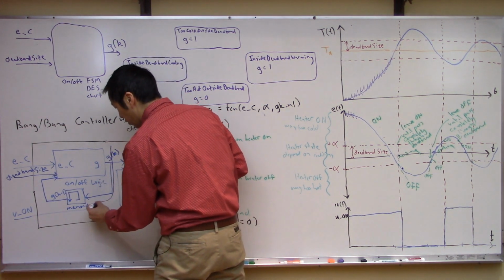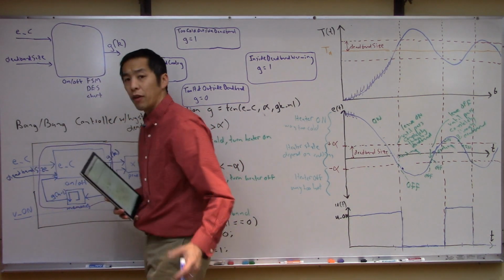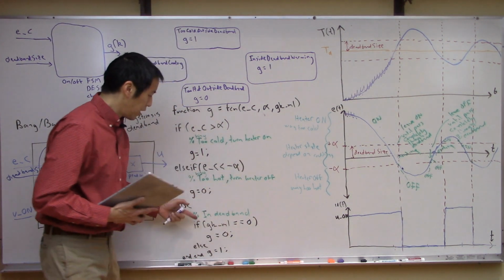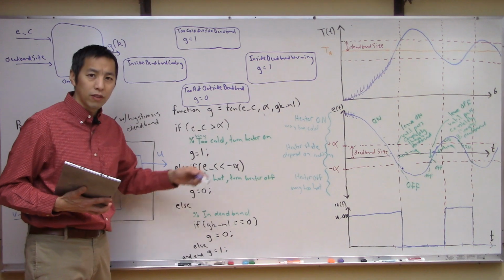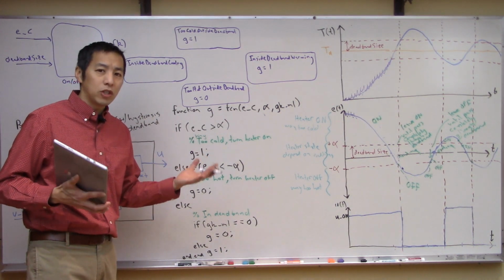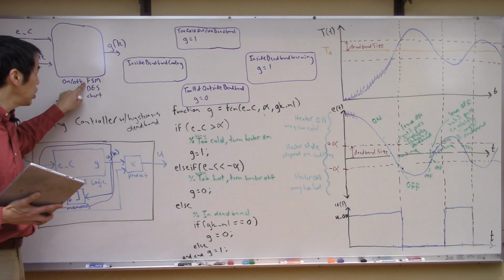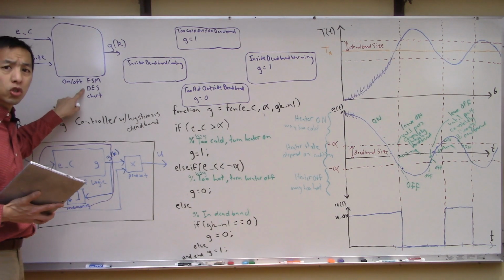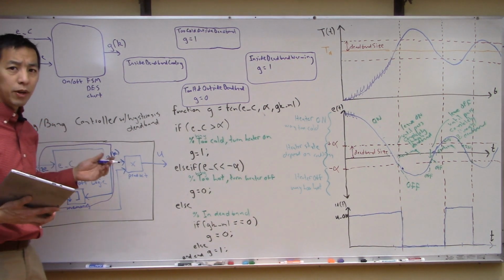So really, what I would like to do is you can actually think about encapsulating this purple box. All of this was capturing this logic of those 4 different states, and here's the kind of if-then-else statements that would get you that behavior of how you're transitioning around all these states. Well, the other way that maybe we can visualize this is using what's known as a finite state machine, or sometimes people refer to it as a discrete event system or a chart. Any of these terminologies is fine.